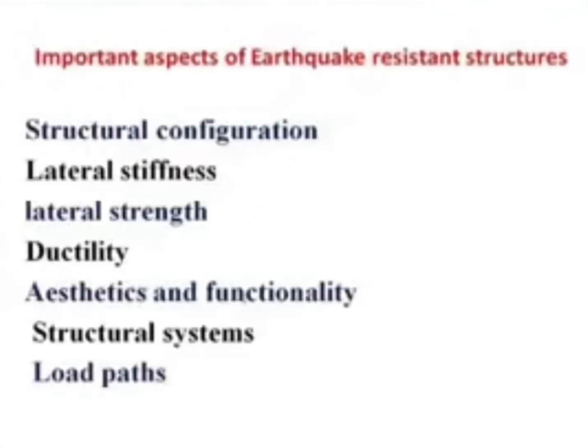Now, these are the important aspects of earthquake. Structural configuration. Is it rectangular, L-shaped, circular? All these things are very important. U-shaped. Lateral stiffness. Very, very important. The columns are providing a major part of the lateral stiffness.